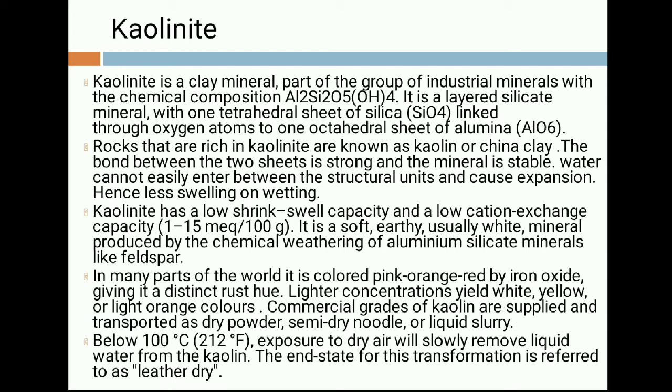Kaolinite has a low shrink-swell capacity and a low cation exchange capacity. So basically this CEC, cation exchange capacity, describes the swelling property of your clay mineral. As kaolinite has less CEC, it has low swelling property. It is a soft, earthy, usually white mineral produced by the chemical weathering of aluminum silicate minerals like feldspar. Means if feldspar is weathered, we'll get more amount of kaolinite.